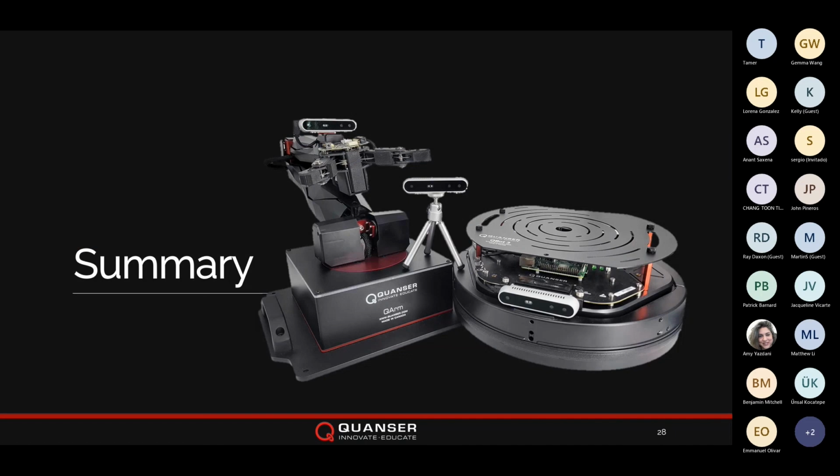To summarize, in this webinar, we talked about how images are processed digitally and the importance of cameras for different robotic scenarios. We then ran 3 demos in increasing levels of complexity to be able to understand image processing and what can be done with our QUARC vision libraries. After introducing some camera basics, we did visual servoing with 2 of our Quanser products. We first used the QBot 3 to do object tracking in 1 dimension, and finally we used the QArm to do object following in 3 dimensions.